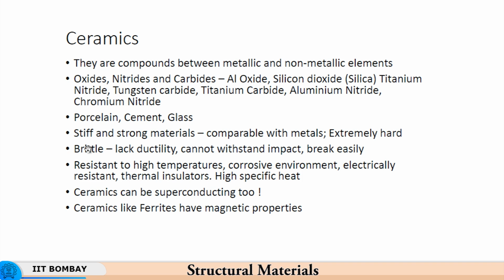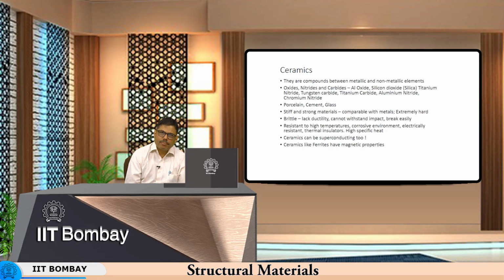So they lack ductility, they cannot withstand impact, and therefore they break very easily. Impact can come from mechanical means, or from what is called thermal shock, meaning you heat a ceramic and immediately cool it very rapidly, it will crack because of thermal shock. Ceramics are usually insulating electrically as well as thermally, but you can have certain compositions of ceramics which can be superconducting also. The 1, 2, 3 superconductors were essentially made from ceramics.